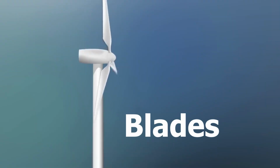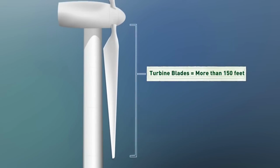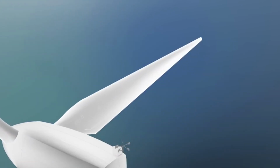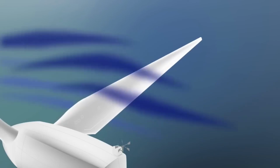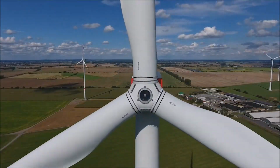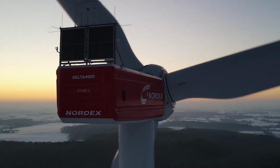Wind turbine blades resemble the wings of an airplane. Wind flows over the blades, creating a lift, similar to the effect on airplane wings, and causes the blades to turn. Aerodynamic properties are crucial in determining how efficiently the blades can extract wind energy. Blades start to spin when wind speed reaches 6 to 9 miles per hour. This starting wind speed is known as the cut-in speed. As wind speeds increase, so does electricity production.